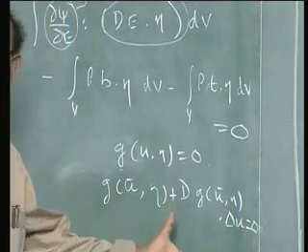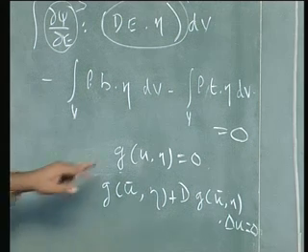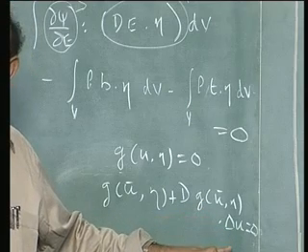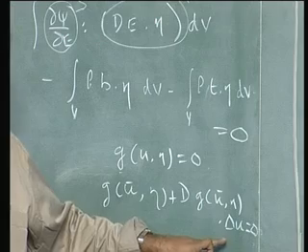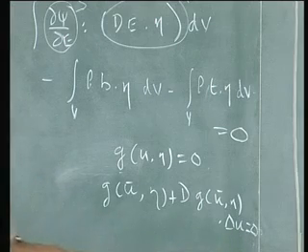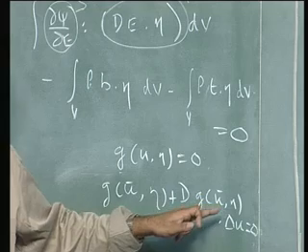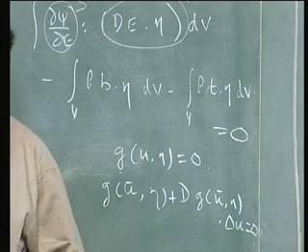So this is what will be the Newton-Raphson scheme. So the directional derivative of g along Δu is what one requires in order to perform a Newton-Raphson scheme, and this is what would result in what is called the tangent stiffness matrix.